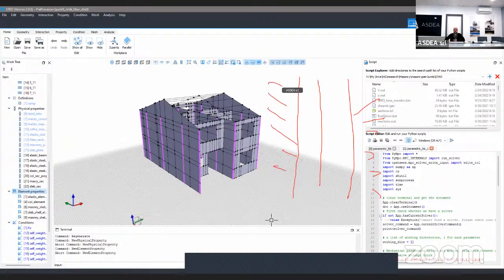With this beam, you have to create a contact, an interaction that goes in this direction, so master and slave, and then you do the same with another interaction, master towards slave. Now, to these two interactions, you need to assign two different local axes. On this side, the local axis should point in this direction, and on this side, the local axis should point in this direction. For contact, the normal axis in 2D is the dy direction. In 3 dimensions, it is the dz direction, or let me check if it was dz or dx. I will do a quick check in just a second.